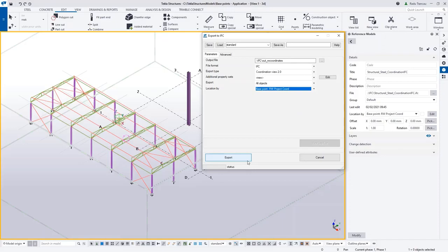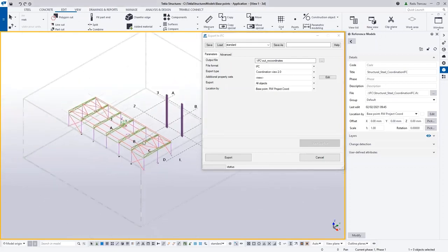Make sure whenever you're doing both the import and the export exercise to get a project coordination base point, which you may receive from somebody else, from somebody who's giving you the IFC, or as we've seen, you may deduce either from the IFC file straight away using that class for Tekla exports, or just by going back and forth and trying to guess your coordinates.